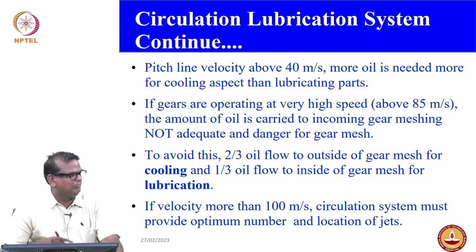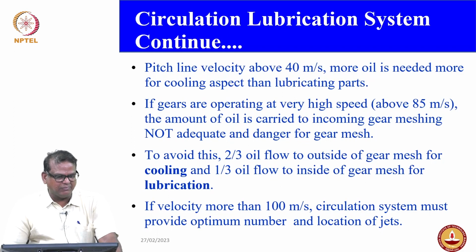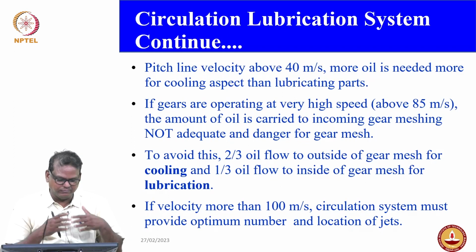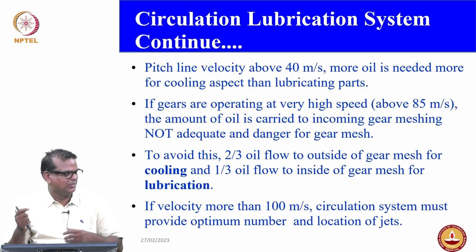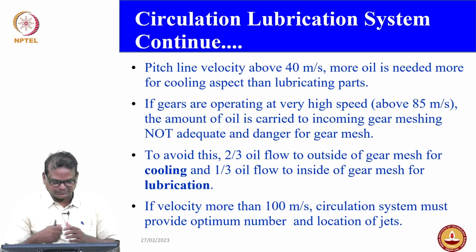Obviously, the number of contacts will be more as the speed increases. So, the heat generation would be more. So, you have to give adequate lubricant, not just for lubricating purpose, it should remove the heat. So, that is how you do the energy balance.